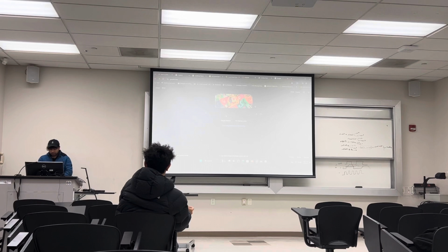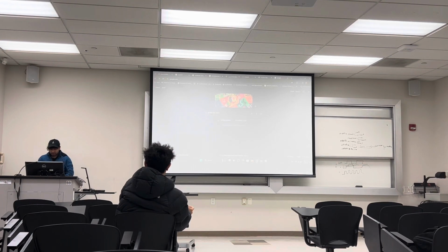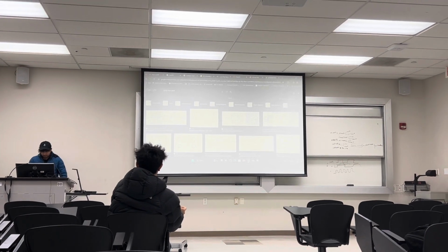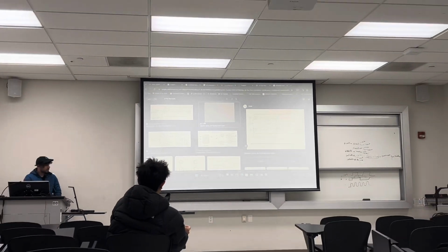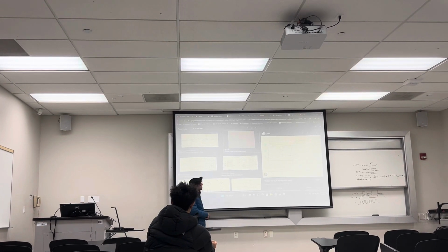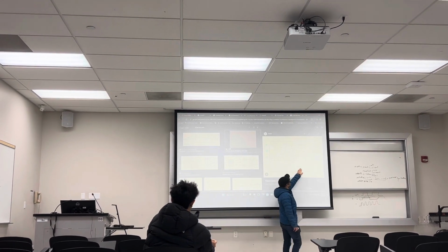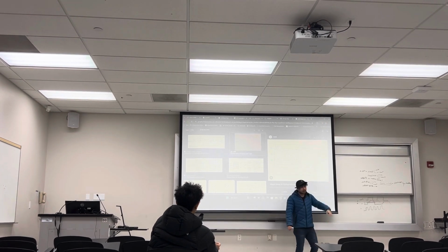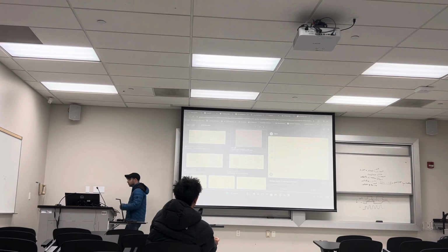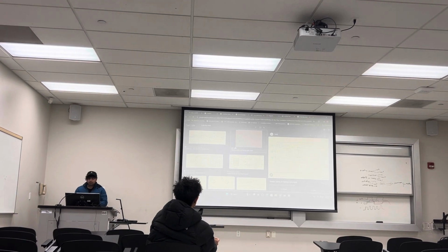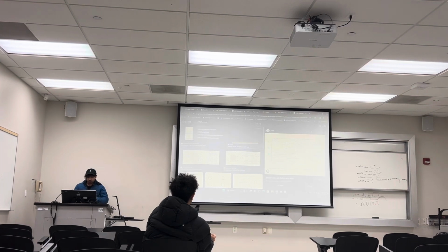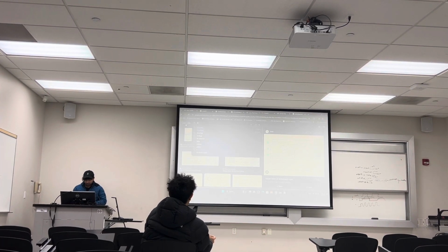If you search JK flip-flop with reset, look, this is for example a circuit with reset. The only difference is that the reset part has one more input on one of the NAND gates, and it's not mandatory. You can design the simple structure or this one with reset. And then after you design that, search 4-bit counter, 4-bit.